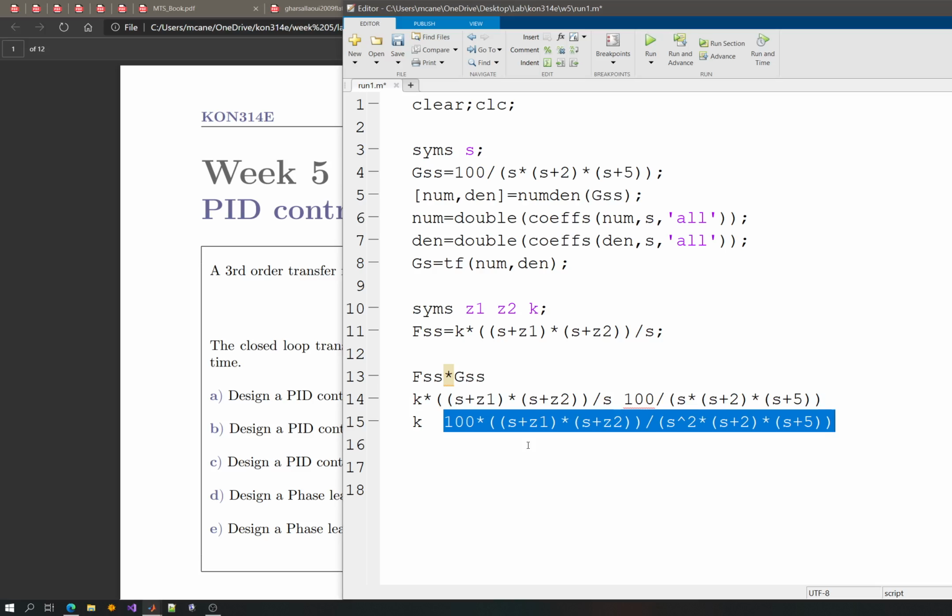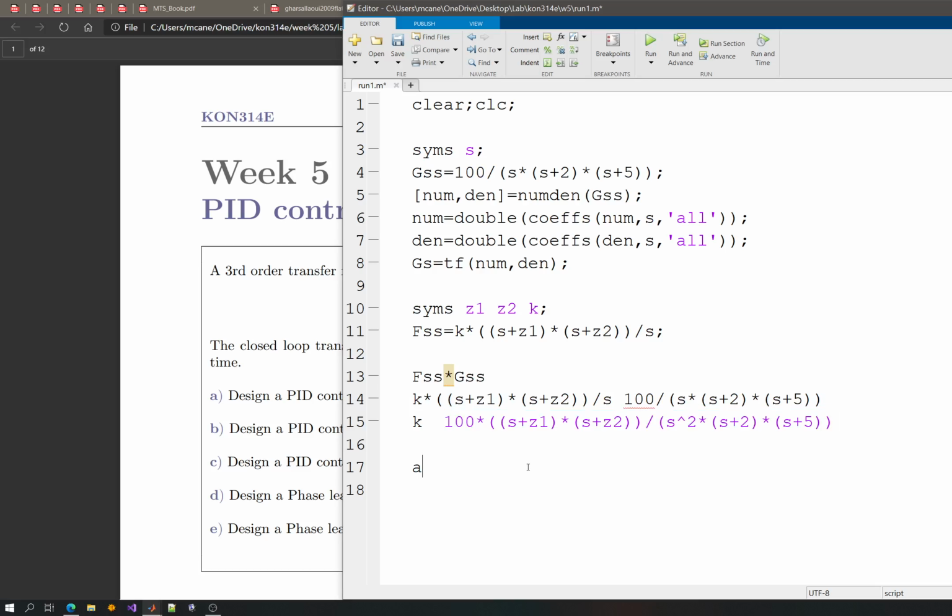Since the most general version of this PID controller is a second-order controller structure, it can look like this: (a s squared plus b s plus c) divided by (d s squared plus e s plus f). This is the most general transfer function or controller structure that I might want to use. This has another representation that I can show you. It looks like this.